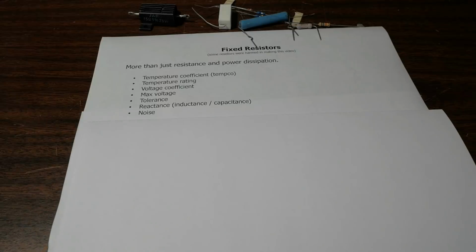And you'll see that used in devices like multimeters, where they'll have several series resistors to help widen the gap, because you'll have these devices able to measure upwards of 1,000 volts, and you want to have a better safety clearance there. Next is tolerance.